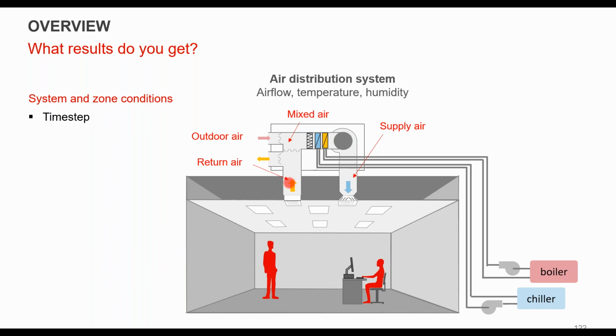much more specific data. So you could look at a specific hour. You could say, I want to understand, is my economizer working, right? You might look at the damper position, the mixed air condition, and your supply air and return air, right, to figure out, is that mixed air what it should be? Should it be economizing for that time period, right? The other data point that's not shown here is the outdoor air condition, right? Is that within the range of your economizer activating?